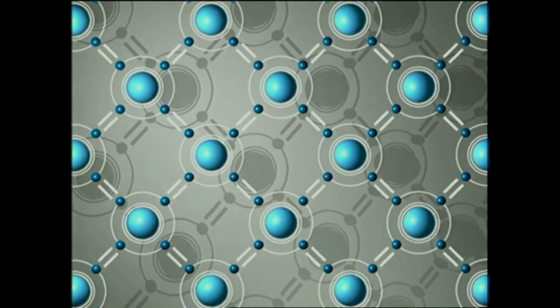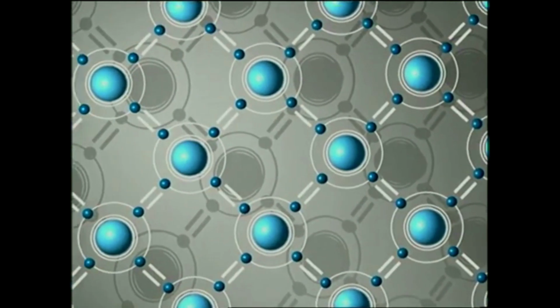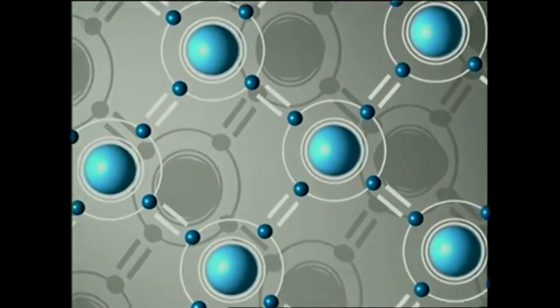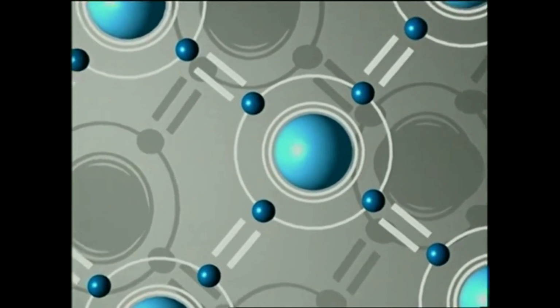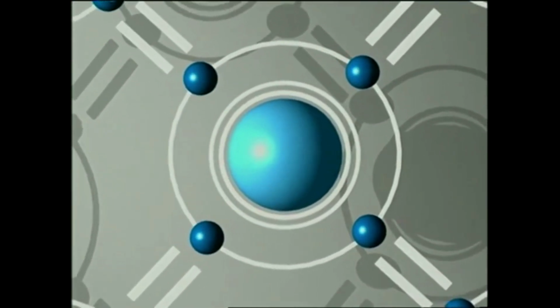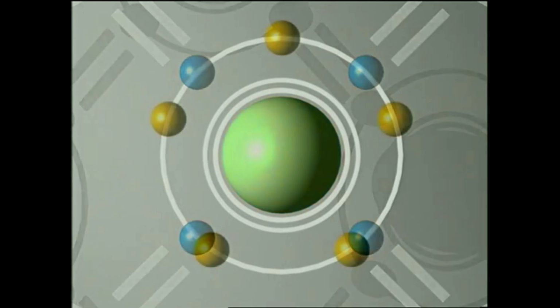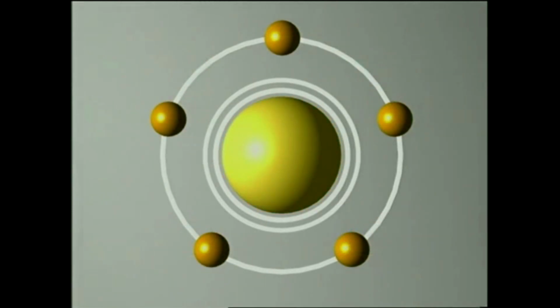Silicon is a semiconductor. Its atomic structure looks like this. Each silicon atom has 4 outer electrons. There are no free charge carriers. The pure silicon monocrystal is non-conductive at room temperature. To make it conductive, small quantities of specific impurity atoms, such as phosphorus, are built in.